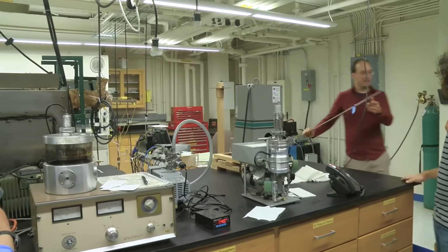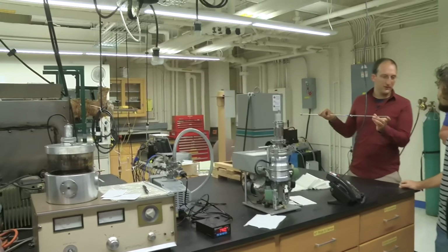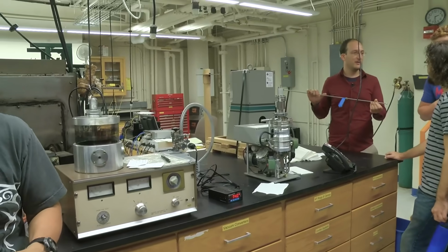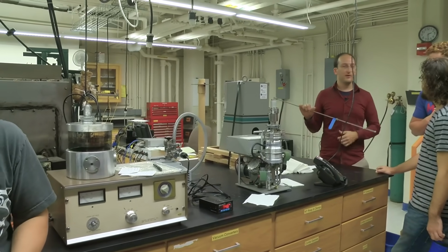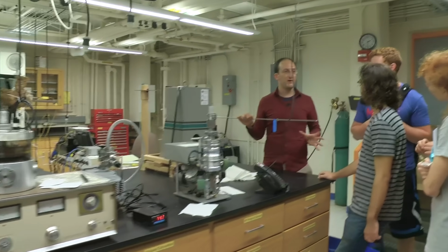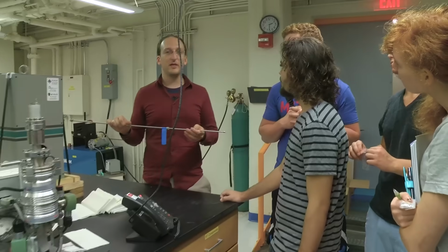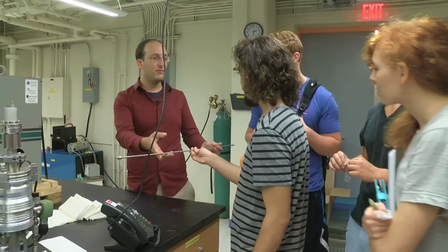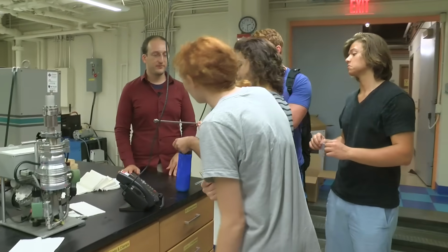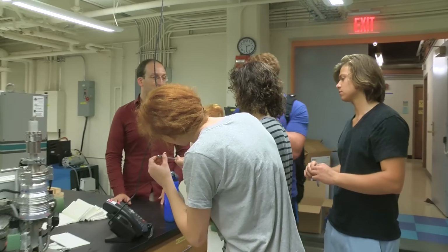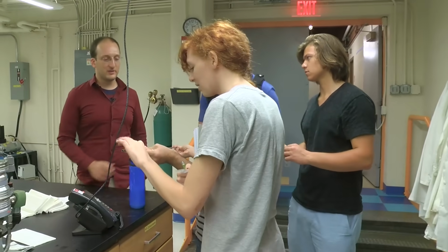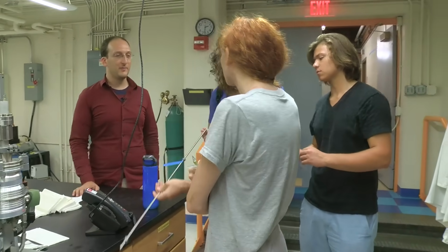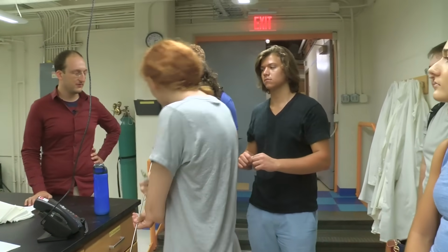This is Swagelok tubing. It's got a 2-piece ferrule, which makes a metal-to-metal seal for moving liquid or gas, and it takes an insanely high pressure. So actually, over in the next room, we can look on our way out. We've built a reactor simulator, like an experimental reactor that replicates all the conditions except for the radiation. We had to make it entirely out of Swagelok tubing because this stuff can hold the pressure and the temperature without deforming too much. So when you want to make an absolutely airtight seal, use Swagelok or things like it. This is stainless steel, yep. They make it out of titanium or other things too, but stainless steel works for us.